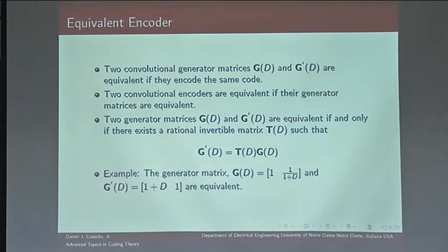So you have a different correspondence between input sequences and output sequences in those cases, and that can be used to affect a property of a turbo code where it has desirable weight properties or distance properties. It gives it extremely good performance in the low signal to noise ratio range.